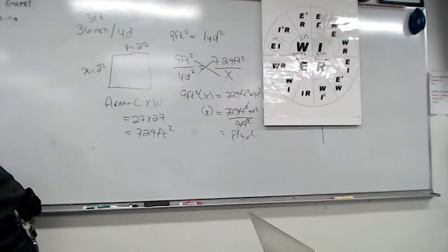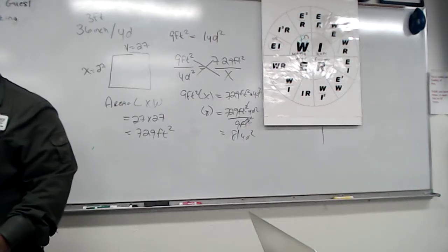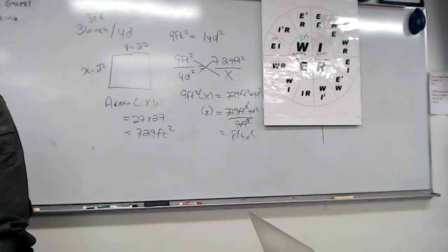Half inch depth. Where is box fill? Y'all know? 314.16. Trying to see if I got a tab for it. There it is. Box fill. Bam. So you look at table 314.16. It says you measure box 3, and it has a depth of 1.5 inches. The volume is blank cubic inches for this box per the NEC. Select answer not applicable if table 314.16(A) doesn't apply to this type of box.